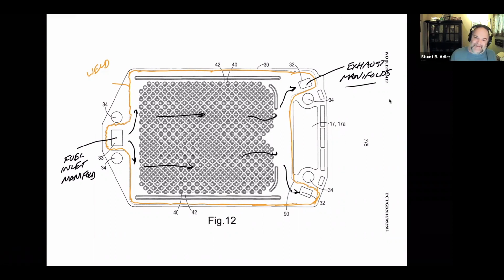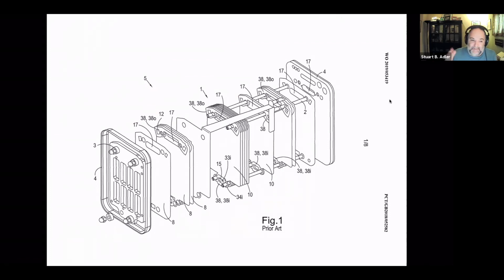We're at low gas density, fairly low flow rates, and you end up with mostly laminar profiles. Laminar flow has a lot of resistance, so that actually can be a good thing because it means that the gas flow distribution ends up being much more uniform than it would be if you were dealing with turbulent flow.